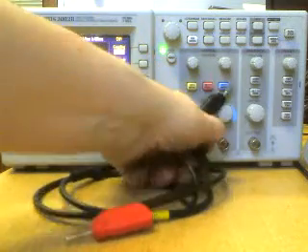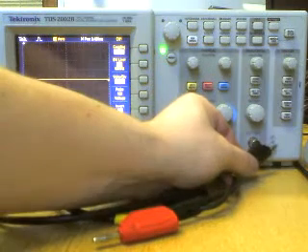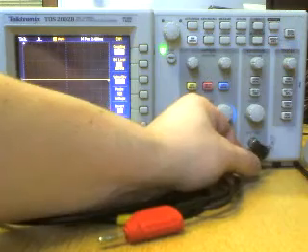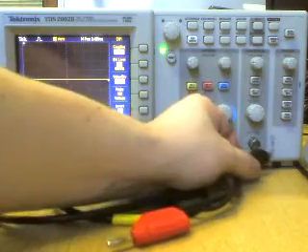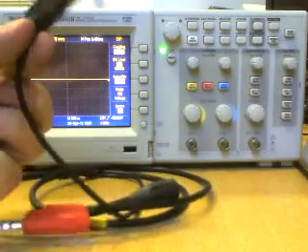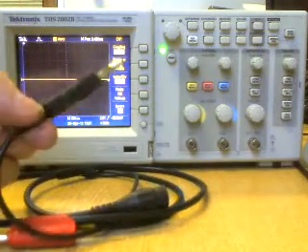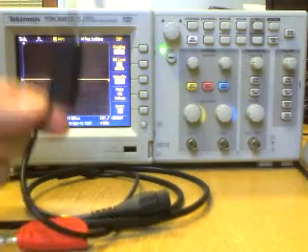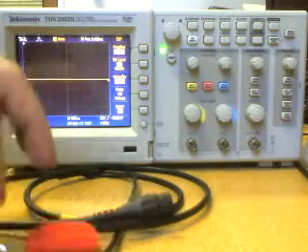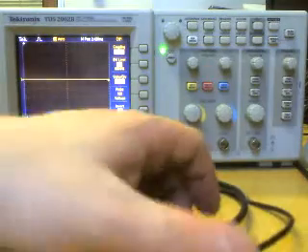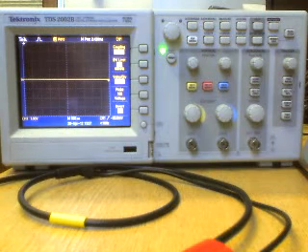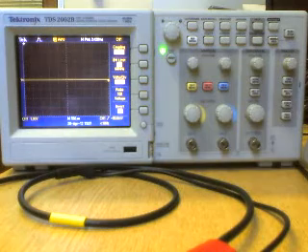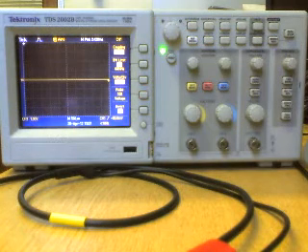Okay, if you take a look on the oscilloscope, it actually shows you a little picture of your socket. So the outer shell, the chassis of the BNC, is connected to ground, so that's a ground potential. Be very careful when you're probing circuits with oscilloscopes and probes, because anything that you connect to an oscilloscope on one side of your probe will always be ground. So it's no good measuring, say, a differential voltage, because that would ground out one half of your differential signal. That's a normal probe. That's what we call a ×1 probe.